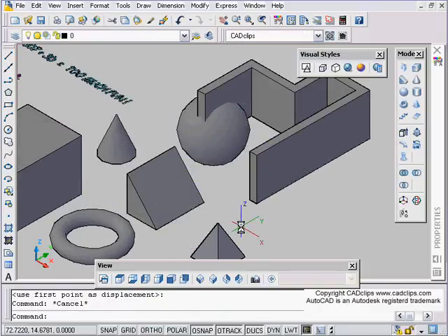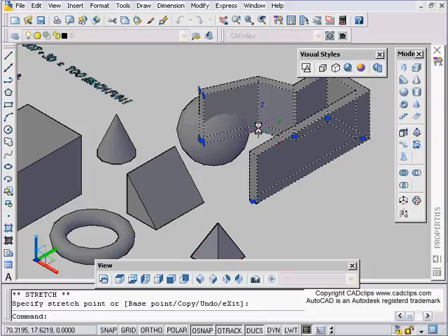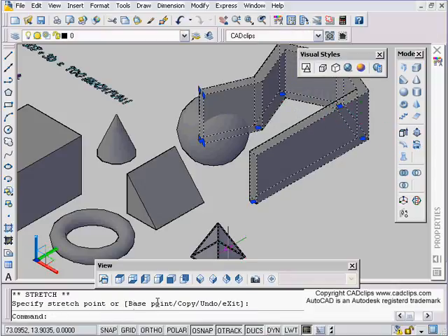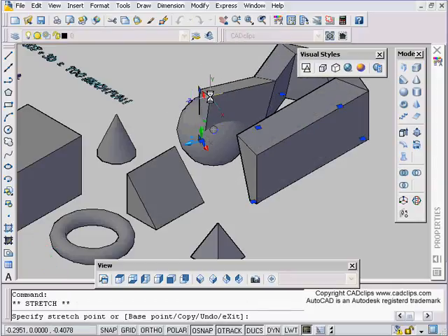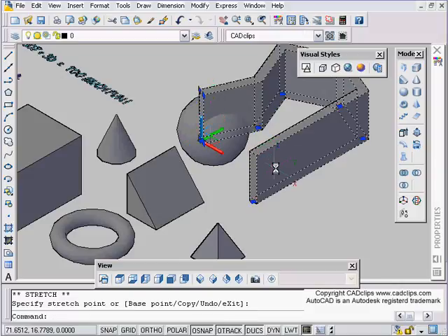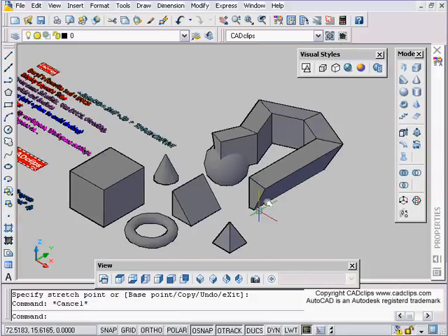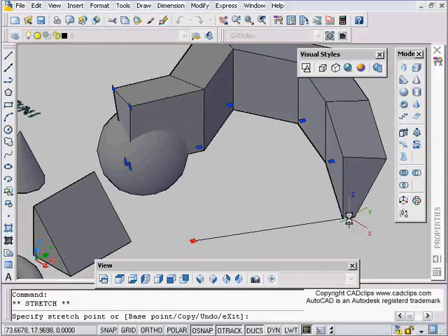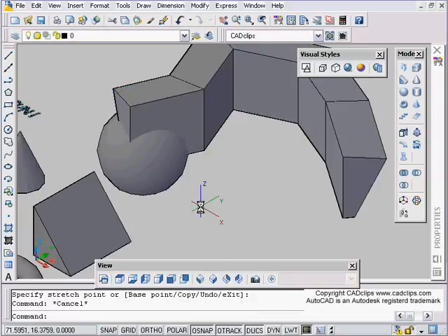Okay, we can place that on there, hit escape. Okay, you can click on it and then you can grab these grips, and you can move these around. This poly-solid in particular, you can do some really neat stuff with it because you can grab these grips and stretch the width factor, etc., like that. Maybe bump that out like that. Okay, so poly-solid, this guy is just a super fantastic tool that you can use to create whatever you want.